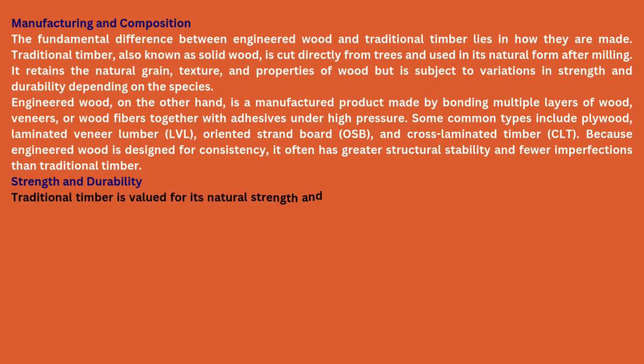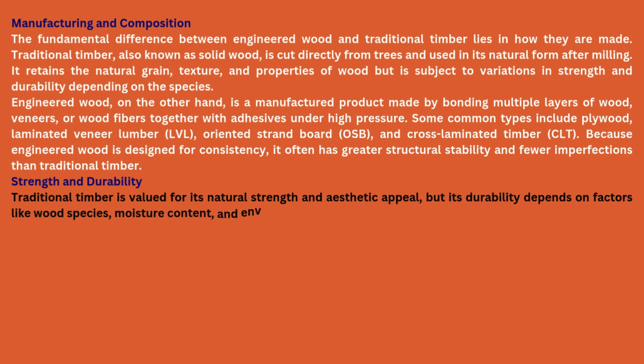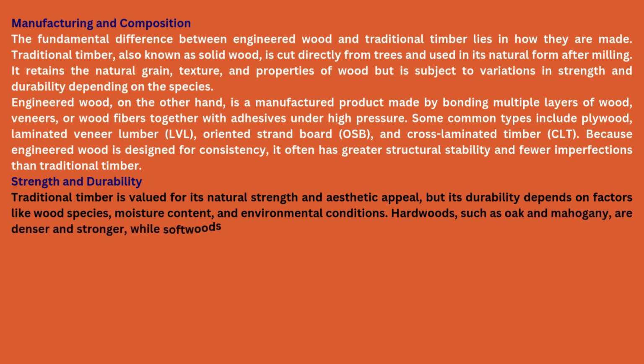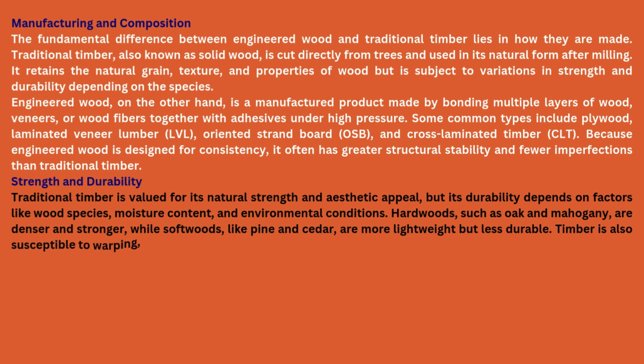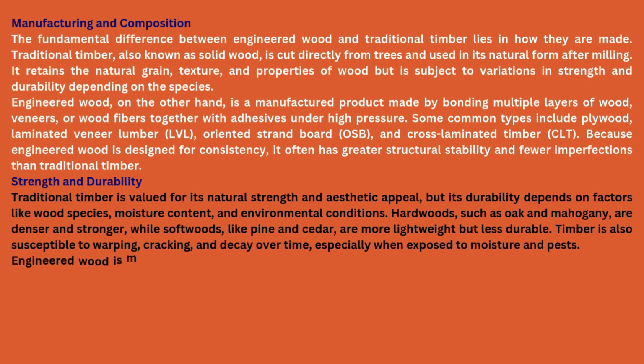Strength and durability. Traditional timber is valued for its natural strength and aesthetic appeal, but its durability depends on factors like wood species, moisture content, and environmental conditions. Hardwoods, such as oak and mahogany, are denser and stronger, while softwoods, like pine and cedar, are more lightweight but less durable. Timber is also susceptible to warping, cracking, and decay over time, especially when exposed to moisture and pests.